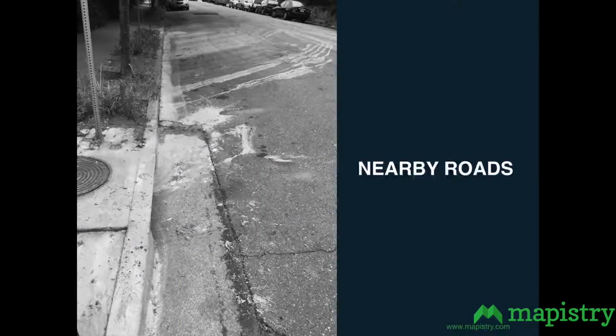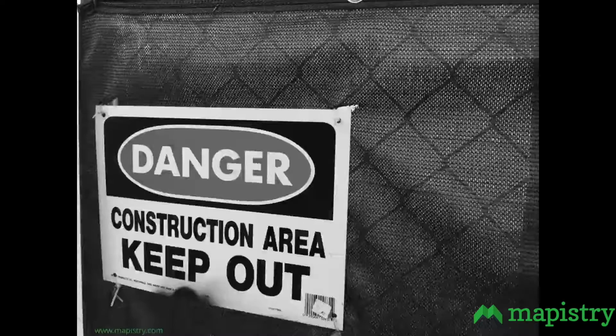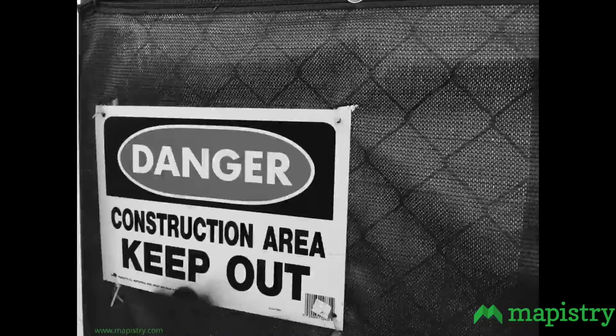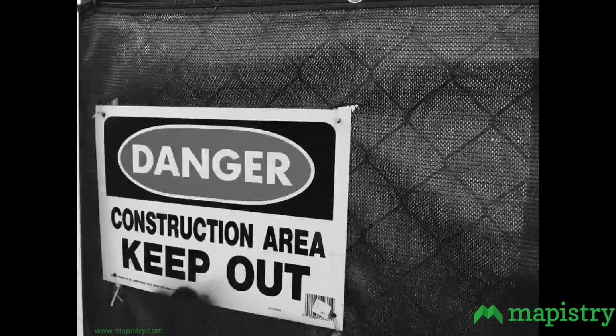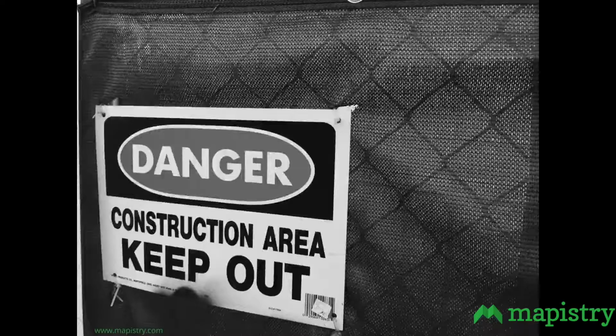Another potential source is just nearby roadways. Maybe there are muddy roads from construction. Maybe there are unimproved lots nearby, or maybe it's a more rural area. Nearby roads are bringing sediments onto your site. The other thing is construction sites nearby. It could be trackout to your site. It could be contributing to the roadways, then gets tracked on via employee vehicles or other traffic. If you have construction next door, it could be running onto your site. It could be blowing sand or debris onto your site. So those are some potential sources to think about if you have TSS issues.